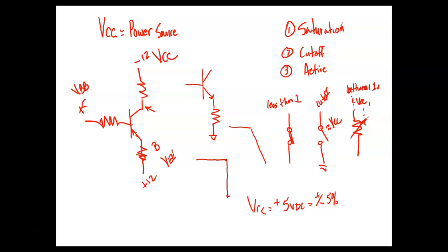So that's what they're telling us there. How long does it take? It's actually giving us the slope. So we can see that on the oscilloscope. I'll show y'all this even on this square wave generator here, because there's no way in the world it can go from a 0 to a 1 or a 1 to a 0 in no time at all. And we call them rise times and fall times. So that's another good thing.